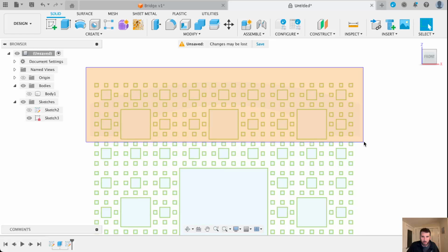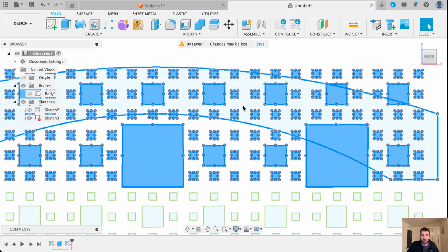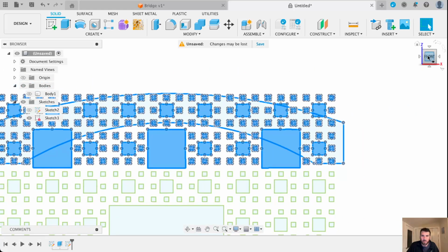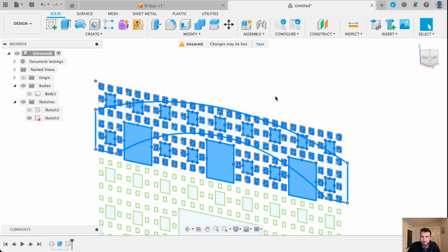So now I'm going to highlight all the squares that I want to cut out of the shape. This area is still highlighted. The selection can add squares, but then it removes it when it's done. So now I can remove this section. And that's a nice trick, sometimes hiding the body if it's getting in the way.